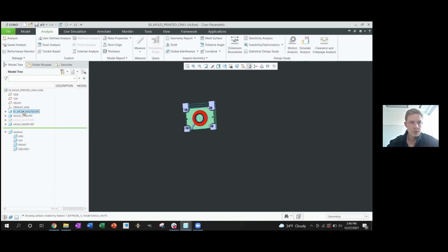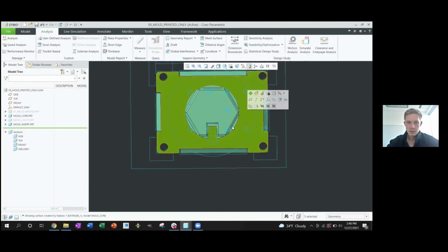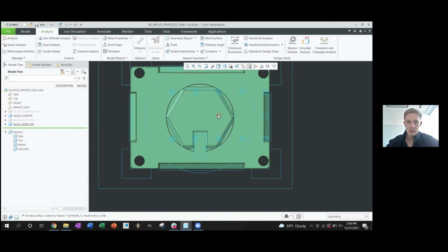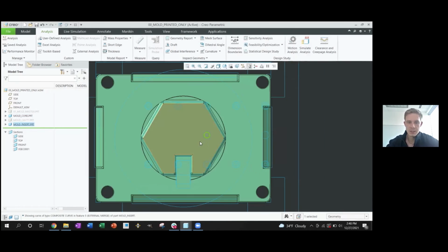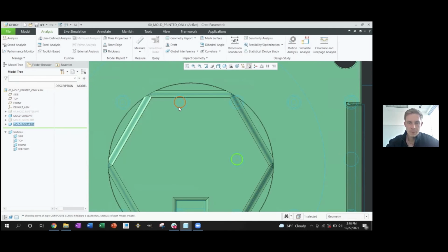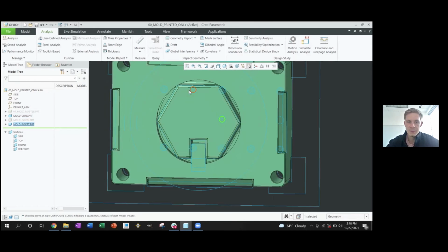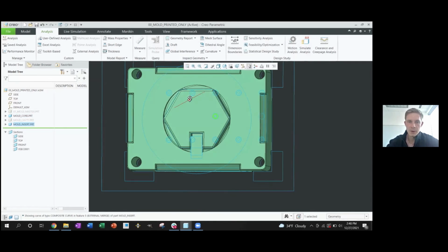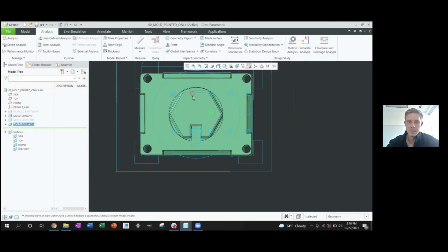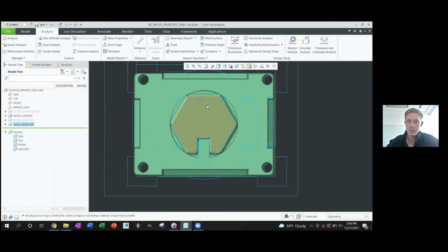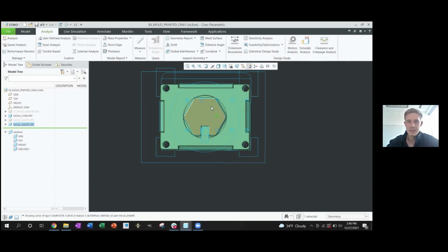What we could do with this part, though, is I'll show a sketch. We have some ejector pin locations on this backside here. So we could actually use some metal pins to press our insert out. For this part, we have ample draft. There's really no need to add something like that into the mix. If we were running with something like a polycarbonate or an Ultem, I would want to use these pins to push this insert out. Those materials tend to be a little tougher to manually eject. But for our purposes, a manual ejection process here is going to be fine.